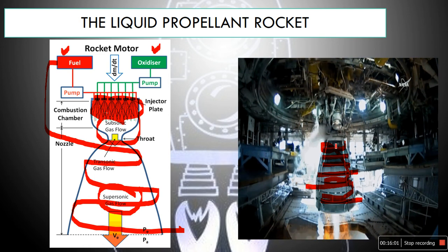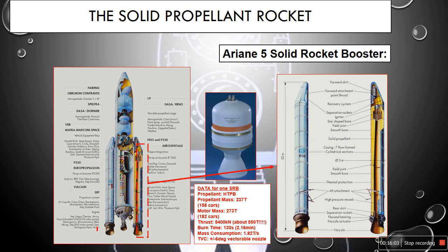If you launch a satellite, if we see in the previous figure, this is the solid propellant, and here is the liquid propellant engine, a multi-staging. Some altitude is carried with the help of solid propellant, because the main disadvantage of solid propellant is that once burning starts, there is no control. But in liquid propellant we can control the flow rate, and the thrust force is in control. We get some high altitude with solid propellant, and then we use the liquid propellant engines to reach further altitude or change the altitude.